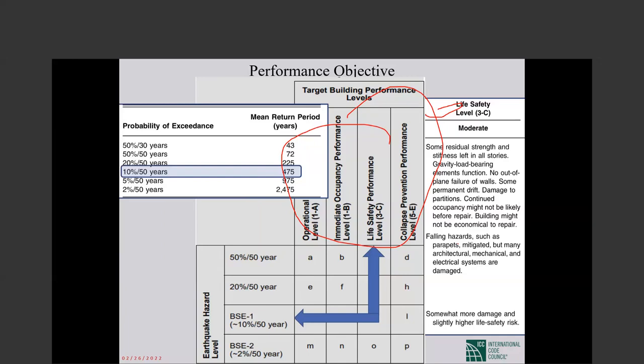Where is it less? When it is the vertical load bearing system. Because if an element carries gravity loads, we don't want too much damage in that. We don't let too much damage on that. We reduce the R value for that. But it's the same element, with less vertical load on it. When the vertical load is carried by other elements, we increase the R value. So it's very important that for life safety, gravity load bearing elements shouldn't fail.